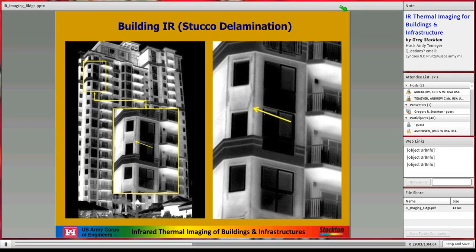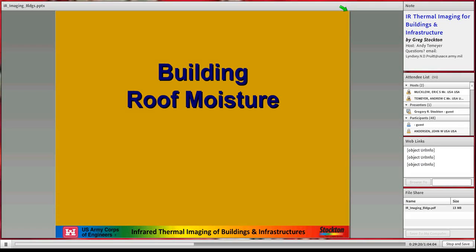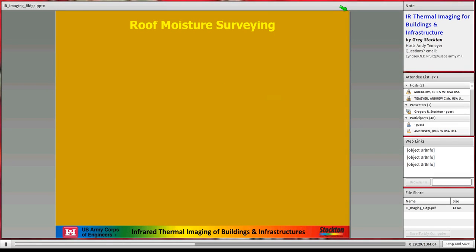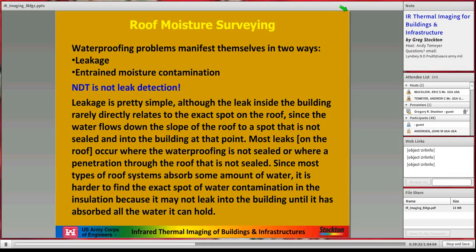And as you can see from this picture, where the little dark spots, the little cracked areas and little dark areas in this picture go all the way down, the whole building is like this. This has the potential to break pieces off and have them fall down and hit people in the head while they're sitting at the pool. So it turned out in this building particularly that the stucco layers were put on in the wrong order, and every bit of stucco was taken off of this building and one beside it.